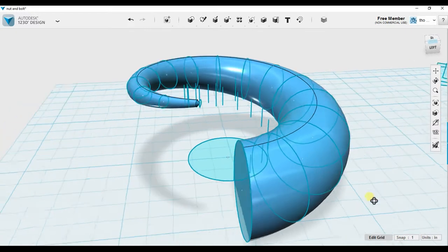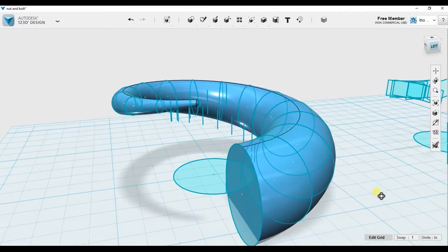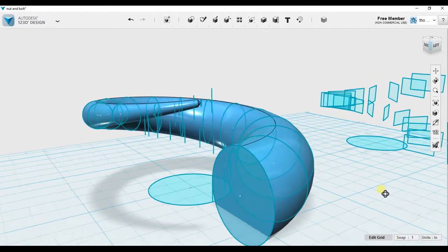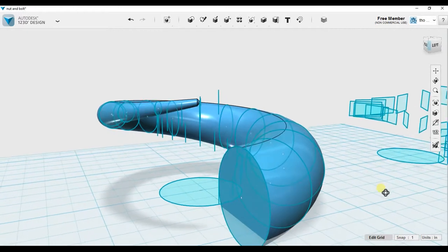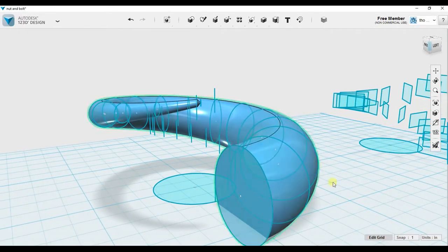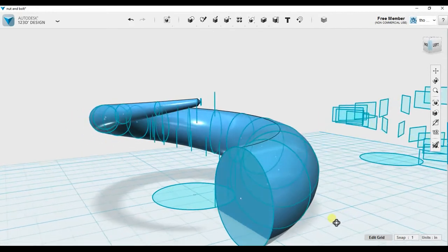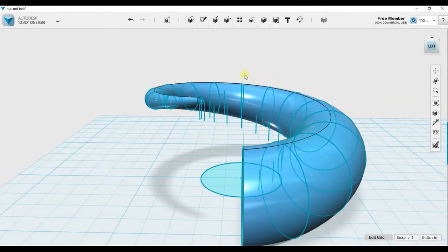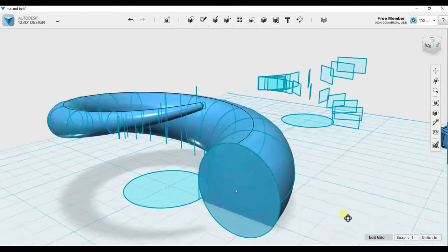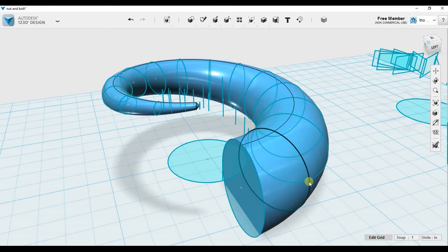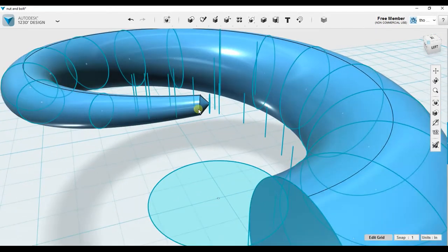And as a little bonus, I showed what you can do with the helix. I use the exact same pattern as at the beginning, except this time I use circles, and then as I moved up 1/16, I reduced the diameter of my circle by 1/16. So I start off with 1 inch here. The next one is 15/16, then 14, 13, all the way around. So this one right here, which is 1/16, or this circle right here, and then I put a chamfer on the end of 1/32.